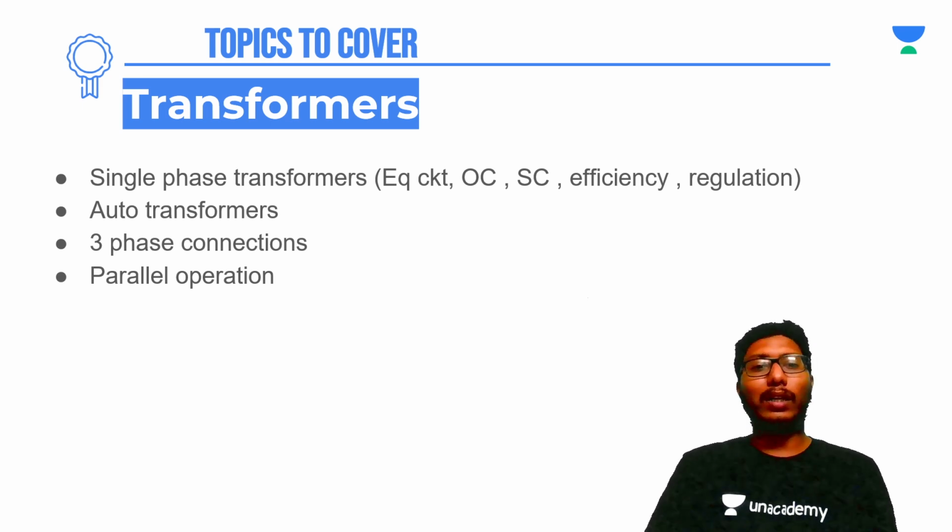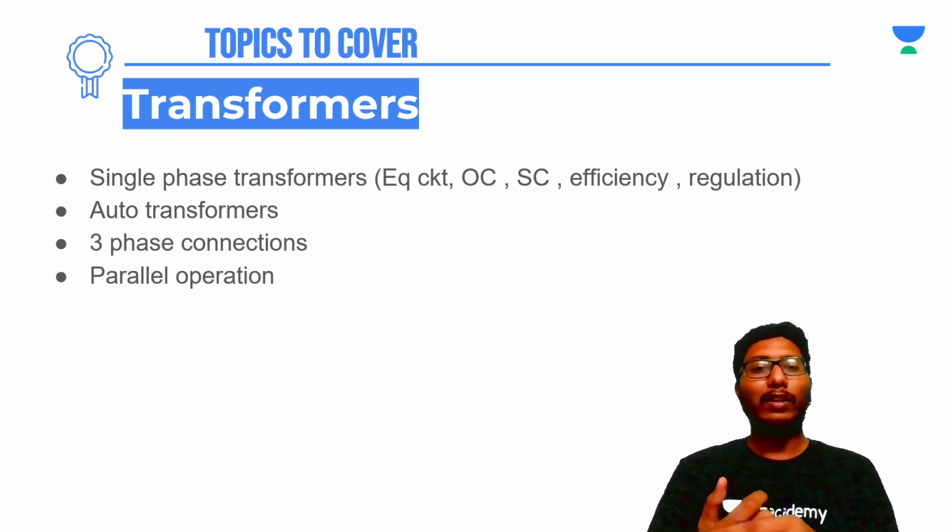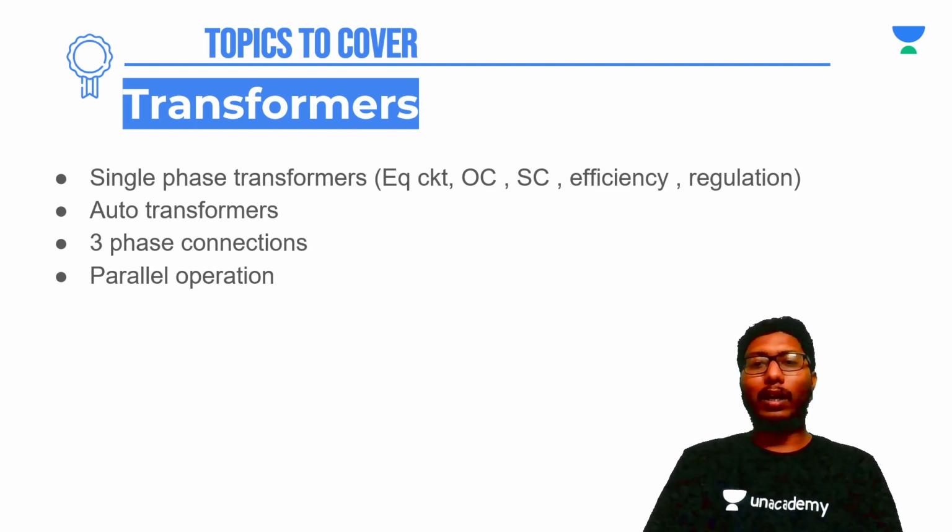Based on the load, the addition will change. If you have capacitance in a tertiary load, it will be leading in nature, and it will be vectorially added in order to get primary winding MMF. From the primary winding MMF, you will get primary current because primary turns will be given. So this is one type of model that you can expect in GATE examination.